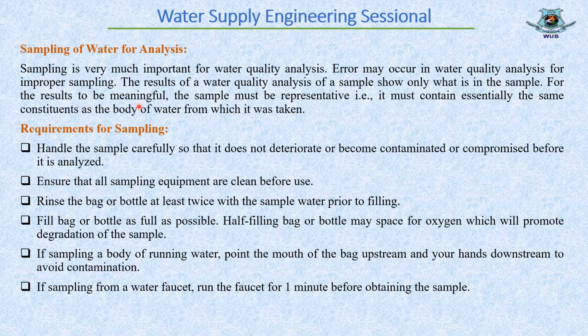For the results to be meaningful, the sample must be representative. That is, it must contain essentially the same constituents as the body of water from which it was taken. Requirements for sampling. When sampling, we should consider the following requirements.